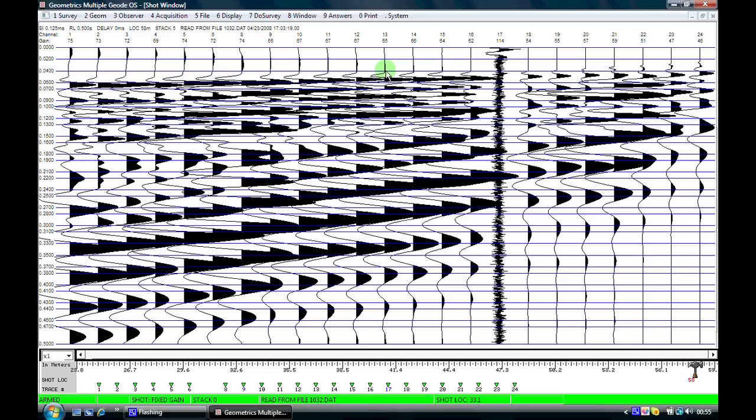In a seismic refraction data acquisition sequence, it is important that we locate the time for our first breaks as accurately as possible, because it's only by achieving high accuracy in this travel time that we get the best fidelity in our data analysis. So, as we're displaying a very long record length at the moment, 1/2 a second, and our travel times are only of the order of 0.05 of a second, probably what we need to do is expand our record.